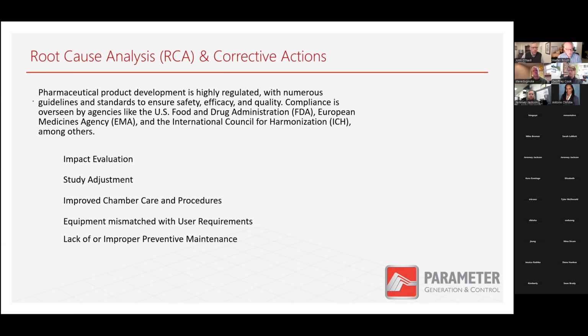Now, the good news is you're in an accelerated condition already, so you're expecting some change. The real question would be, is this excess moisture really going to impact your probably already tightly packaged product anyway? So you could, in your investigation, rationalize continuing the studies as is, because if you do end up with failures, you were at accelerated already.